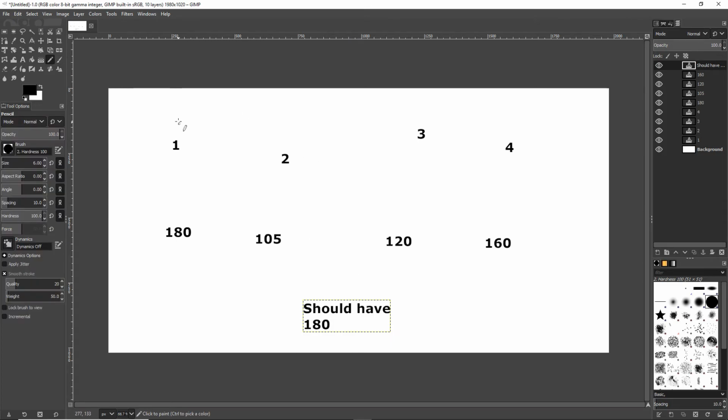Well, 180 is perfect, so cylinder 1 looks good. 160 is really not that far from 180 given the age and the miles on this engine. Now, if the engine had 30,000 miles on it, that's way too much. Something's not right. But if it's got 100,000 miles or more, that's really not that far from perfect. I'm really not worried about it. That's not going to cause a problem.